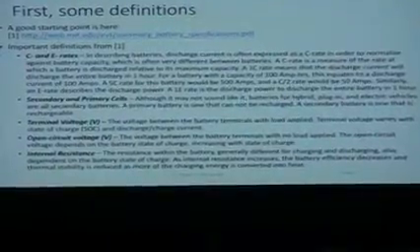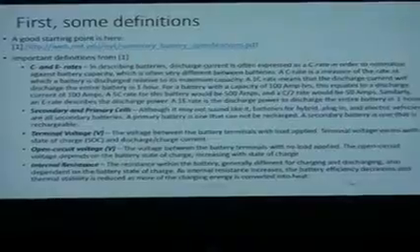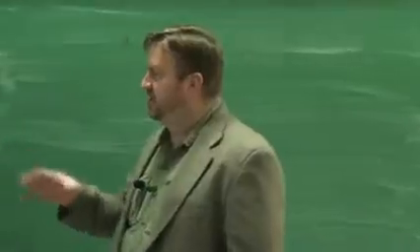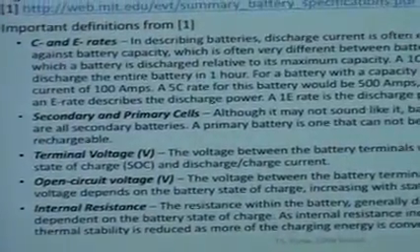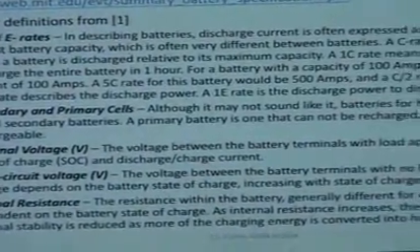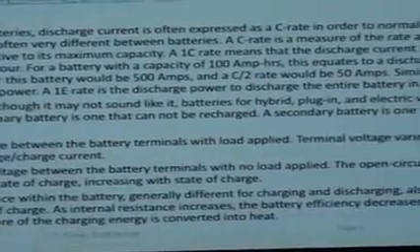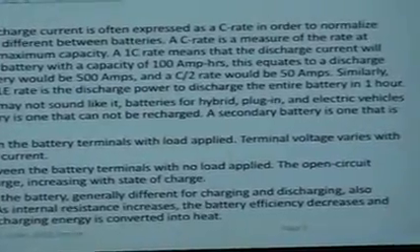Some other things about voltages. The terminal voltage is the voltage that the battery has when there's a load applied. And the load, of course, is resistive in nature, and so that voltage is going to be dependent on the resistance and the amount of current that's coming out of the device. It can be a complicated issue or characteristic. The open circuit voltage is easier. The open circuit voltage is what it sounds like: when the battery is not connected to anything, what's the voltage across the leads?